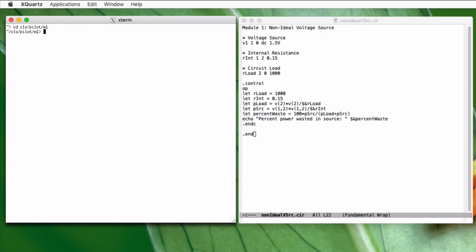And most of the simulators out there basically allow you to draw a circuit schematic using the symbols for resistors and voltage sources and stuff like that. And then what that simulator will do is generate something called a SPICE Netlist, which looks like basically a programming language for describing a circuit. And then the SPICE simulator operates directly on that netlist. Now, for this class, since this is your first introduction to SPICE, I've decided to work with the netlists directly. And this is the way SPICE was originally done.